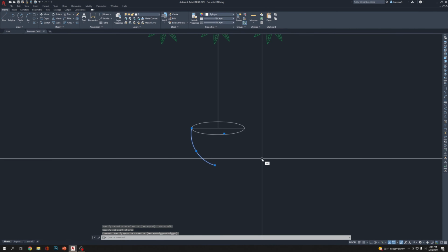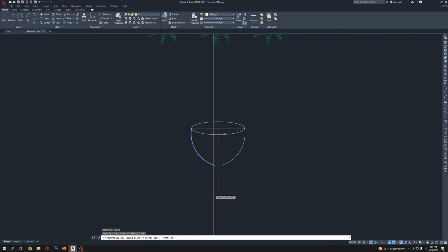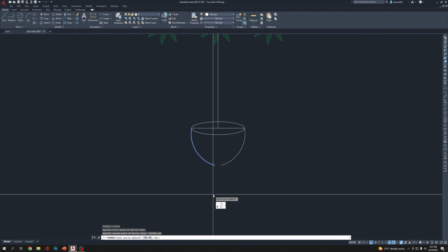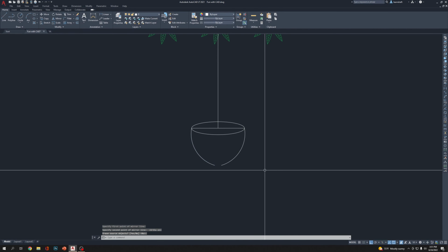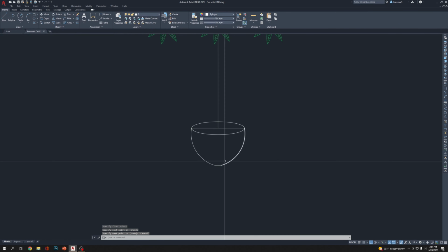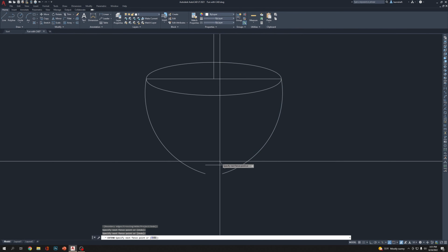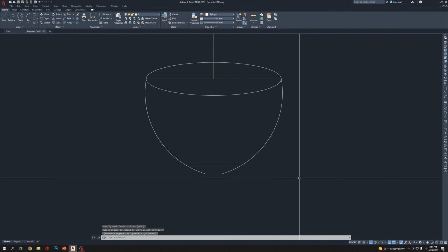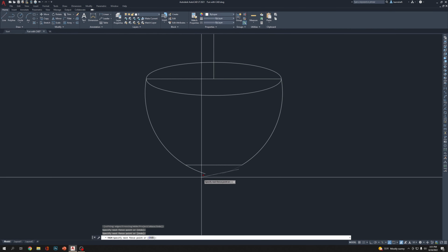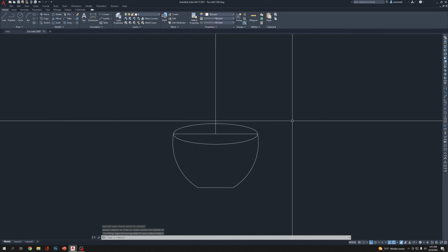Yay! Look like a tab, right? F8. Click, go straight click and then press enter, and then draw a line here which is gonna be a little above the ground. EX, enter. Extend both sides, then trim the roundness from the bottom, otherwise it's not gonna sit there.